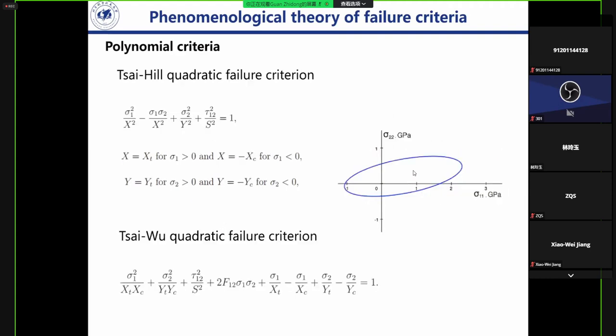To solve this problem, people further developed the strength criteria. The Tsai-Hill criterion is a direct adaptation of the classical Mises yield criterion so that it can be applicable to anisotropic material with different behavior in tension and compression. Furthermore, Tsai and Wu proposed a more general form of the Tsai-Hill criterion. They believe that the existing phenomenological failure criteria are attributed to various special cases of a high-order tensor polynomial failure criterion, with second-order polynomial as the main computational criterion.